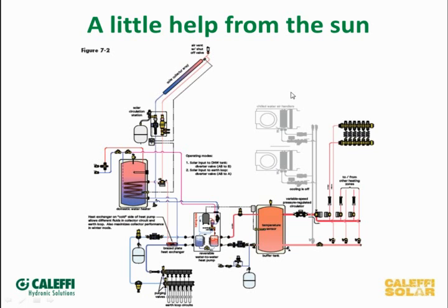I visited a job with Nathan in Soldotna up on the Kenai when I was up there, and he put a system in that had some radiant ceiling panels, which were kind of unique. So he had a ThermoCon tank in there. It was not a geo system, it was a boiler system, but he was doing some spot heating with an aluminum panel that drops right into the ceiling grid, which is nice. And that's another application, we didn't talk about that earlier, maybe, that you can do a ceiling or wall heating system that would run at a low temperature. But those aluminum panels make it a really unique application, especially on a commercial building.